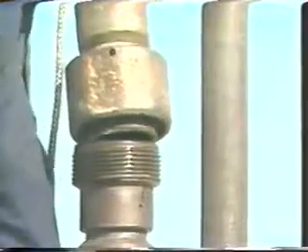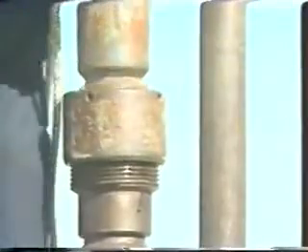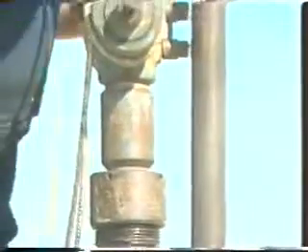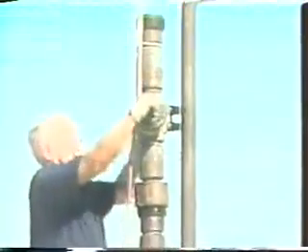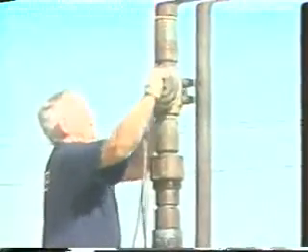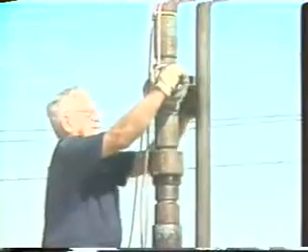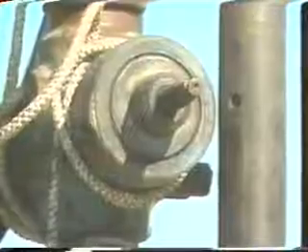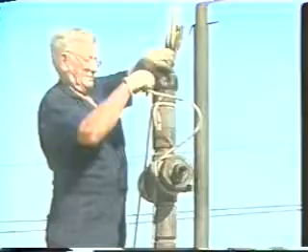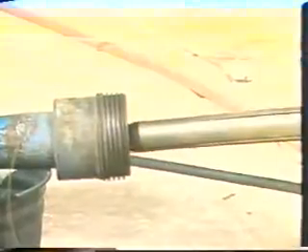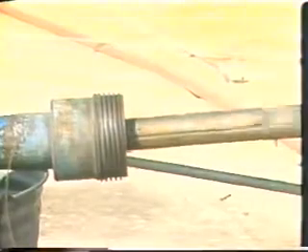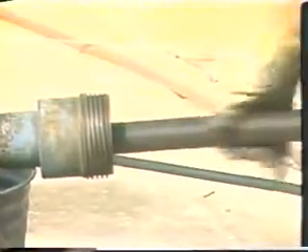With the gin pole in position, the wireline valve may be lifted and placed in position on top of the tree, where it is made up to the tree connection. If a situation should arise that requires the well to be closed at the surface while wireline is in the well, the wireline valve may be closed without damaging the wireline. The tool string is assembled and slid into the top of the lubricator, leaving about 1 foot sticking out of the top of the lubricator.